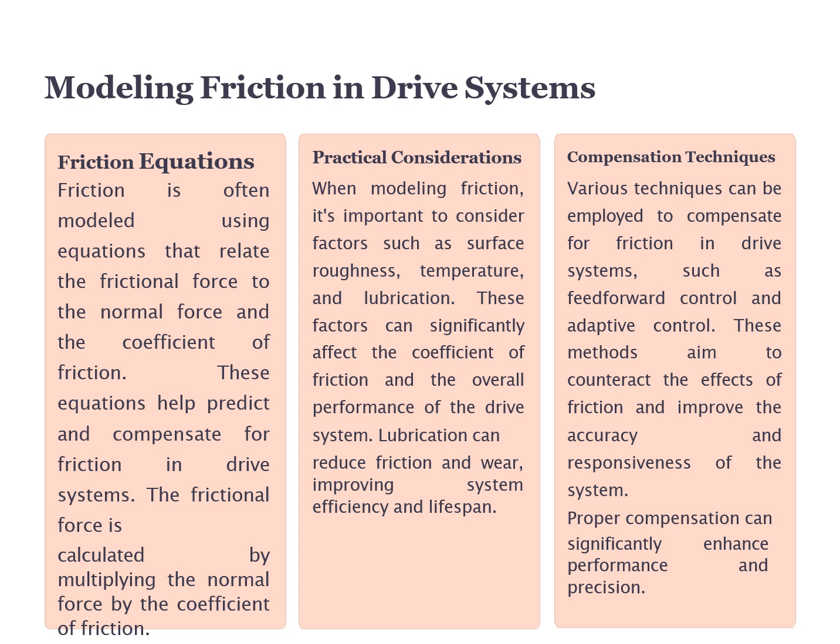In practice, factors like surface roughness, temperature, and lubrication can significantly affect the coefficient of friction. For example, proper lubrication can reduce friction and wear, improving system efficiency and lifespan. On the other hand, high temperatures can increase friction, leading to more energy losses.